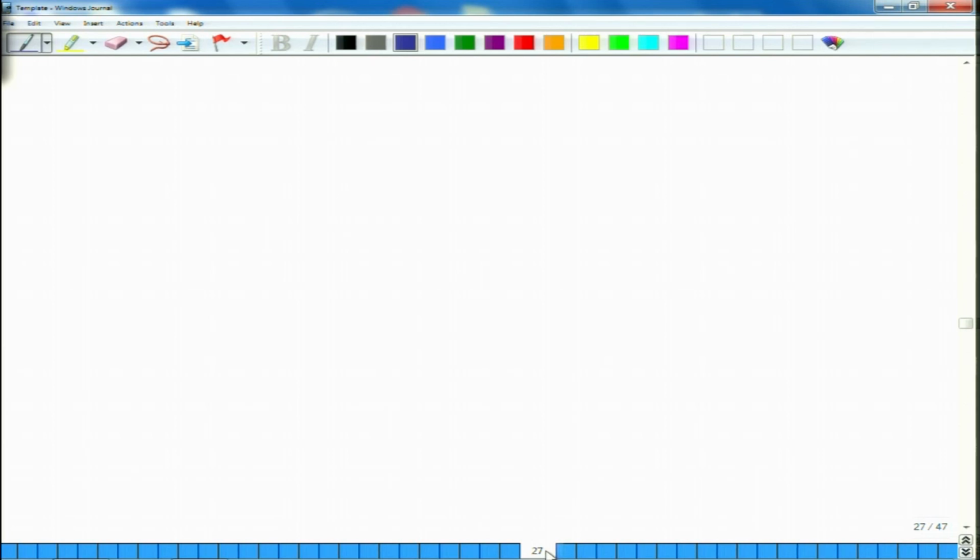So, we will very quickly write down some rules. Whenever we express it in such a format, we assume that each layer orientation is assigned with respect to the x axis. This x axis does not change, it is a universal axis. Then we use these slashes as separators between layers.